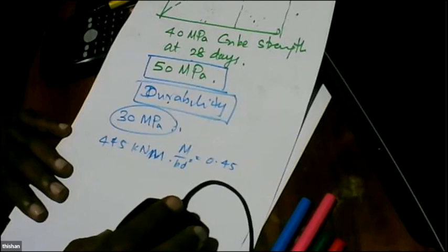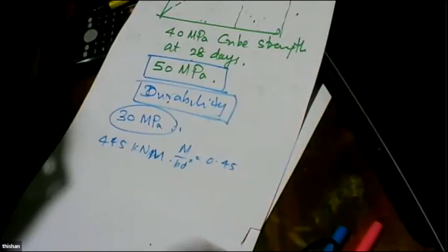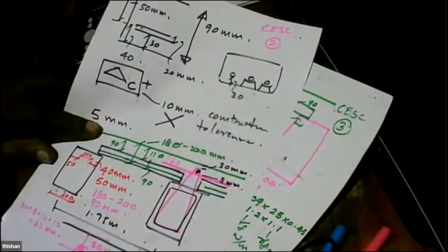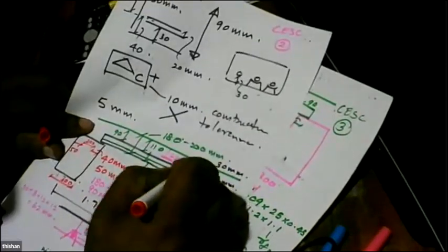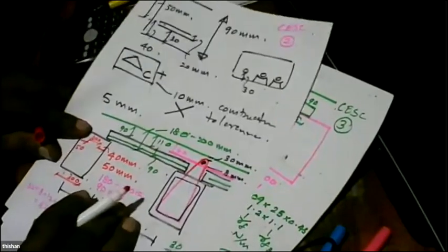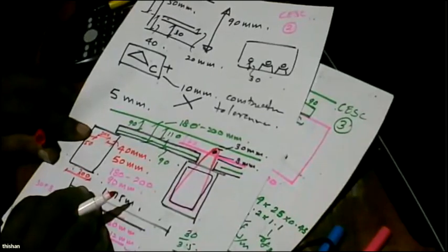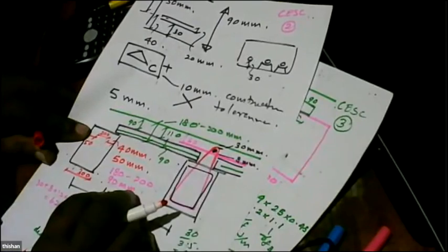There will be longitudinal. You are talking about interface. Somebody is talking about interface here. It's a valid question, but you can see we are providing these links at very close spacing. So we are having double links, this link and this link, and we are going to provide these links around 100 to 150 millimeter spacing. And the moment you do that, you find this interface here is very well looked after.